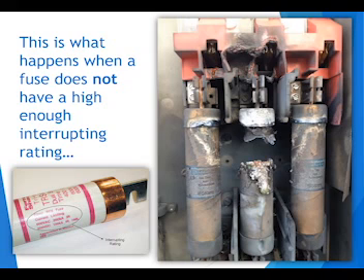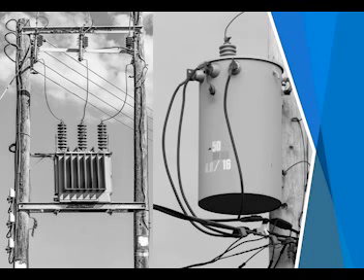Keep in mind that the location of the overcurrent device to where the fault is also affects what that interruption capacity is going to be. So it all starts with the values that we find inside our transformer. We need to remember that a transformer is limited between its input and output. So whatever the kVA rating of the transformer is, if it exceeds that, it's going to trip out the overcurrent devices for the actual transformer.